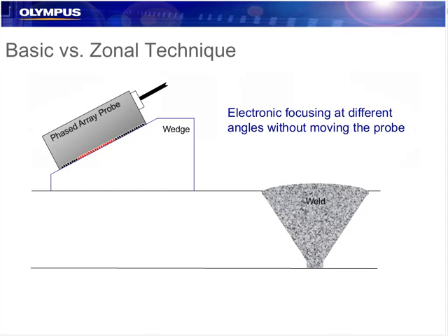When we look at some of the pipeline requirements, here we're looking at a typical weld that we're used to, with a bevel of 30, 33 degrees, something like that. Typically for the general weld inspections that we are probably more familiar with, using sectorial and linear scans, we choose a number of elements and we can fire a sector scan, focus on the weld, with no problem getting the proper incidence angle here. And we can electronically change that and get full volumetric coverage and good detection of our defects.